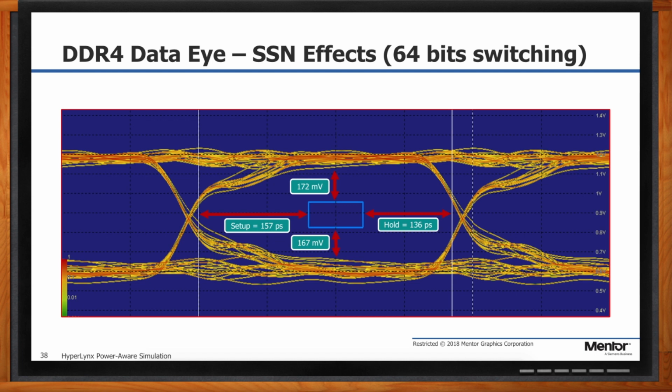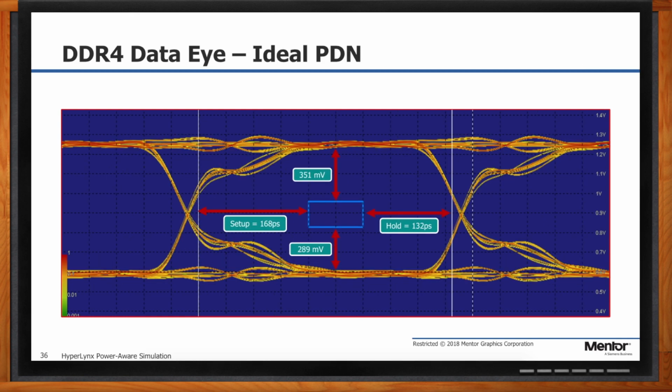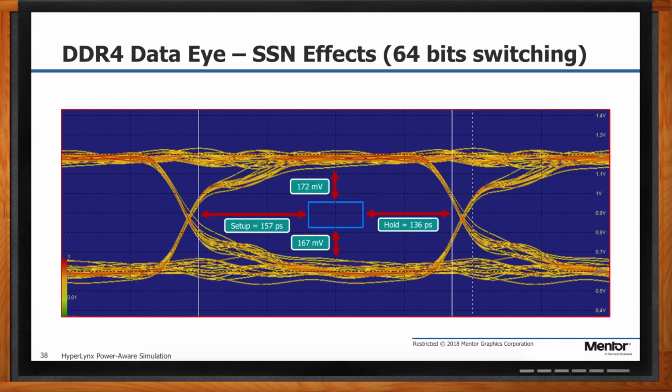The other thing that is really interesting here is that this kind of analysis allows me to violate some of these coveted rules of thumb. Very often, if I'm trying to design a high-speed system and I've got ground reference data nets, we're just going to say, well, you've got to be ground referenced from beginning to end. You can't change the reference voltage on any of the nets because we can't afford the inductance for the return path to go from plane to plane. And very often people will try to do that, and they're increasing their cost of the design sometimes because they're trying to put additional planes into the design, and they're making their stackup bigger. They're making their board more costly.